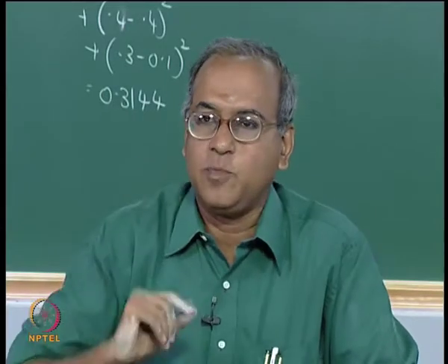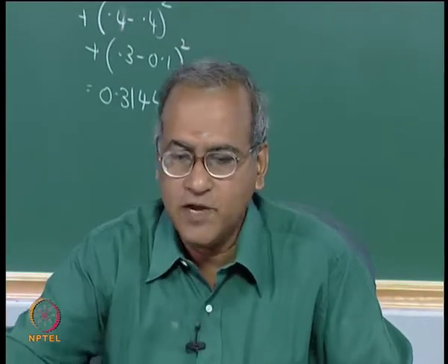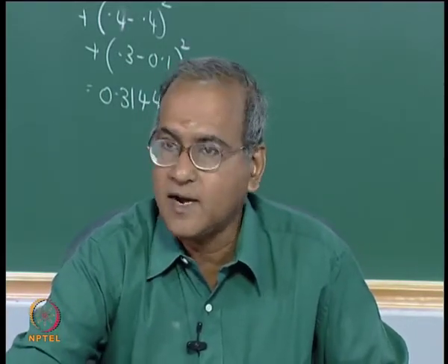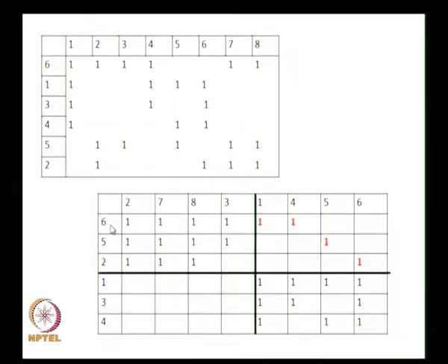Third one is machine duplication. Now, if we look at this solution, very clearly we understand that if we duplicate machine number 6 into the second cell, we can eliminate 2 intercell moves. So, first cell will have 2, 5, 6, second cell will have 1, 3, 4, 6. So, components or parts 1 and 4 will visit the other 6 that will come here.